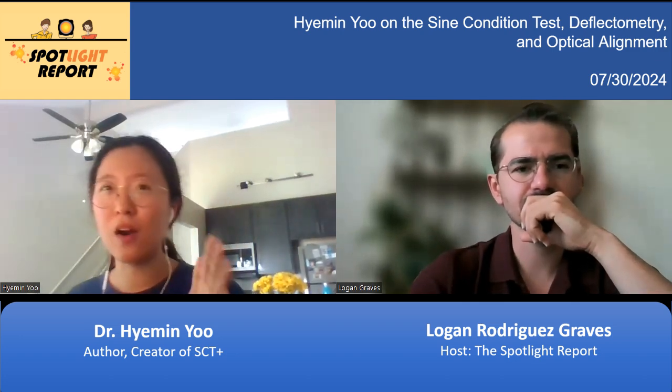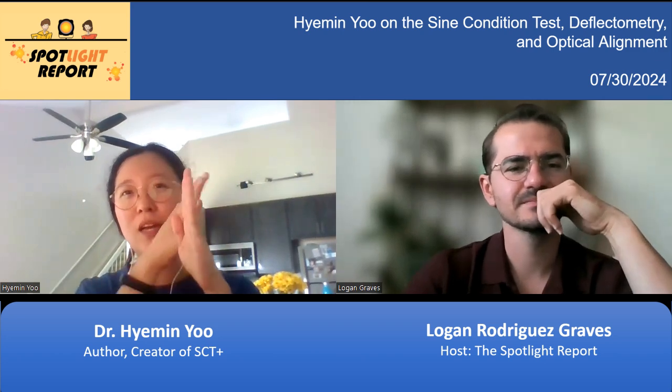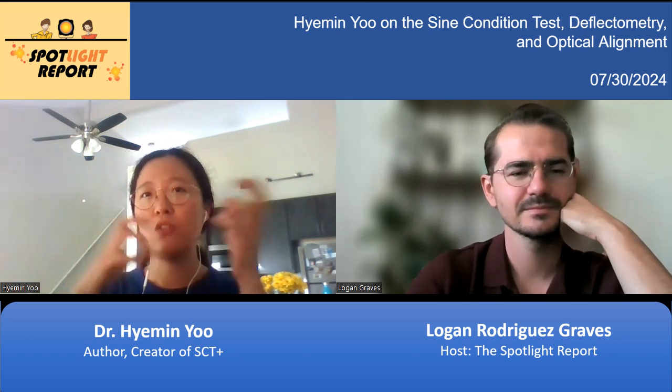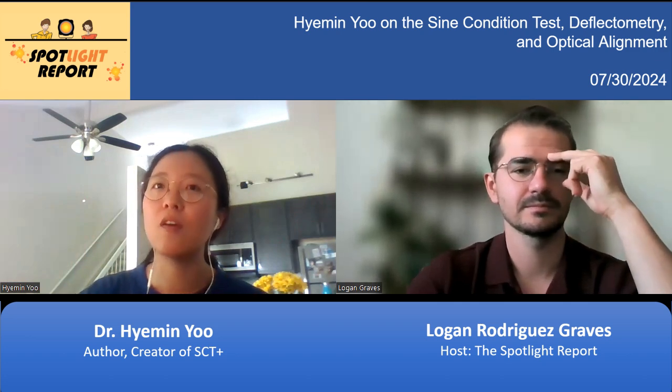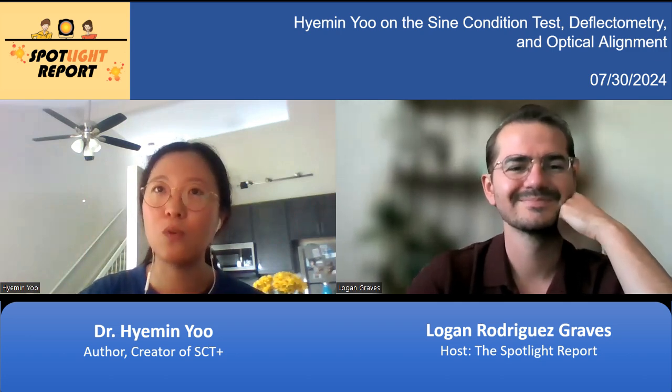The hardest part about that was how to align them. I mean, how do we know if they're calibrated well? That was the problem. So I had to come up with some custom designs, an interchangeable mount for the camera and the return sphere, and also had to do many months of CMM measurement to know all the optic geometry, and it was painful.